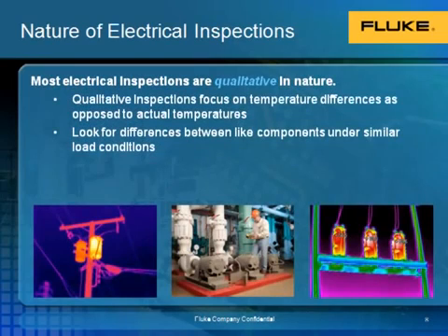Most electrical inspections are qualitative in nature. This means that we focus on temperature differences as opposed to actual temperature. Much of thermography relies on looking at the difference between like components under similar load conditions.